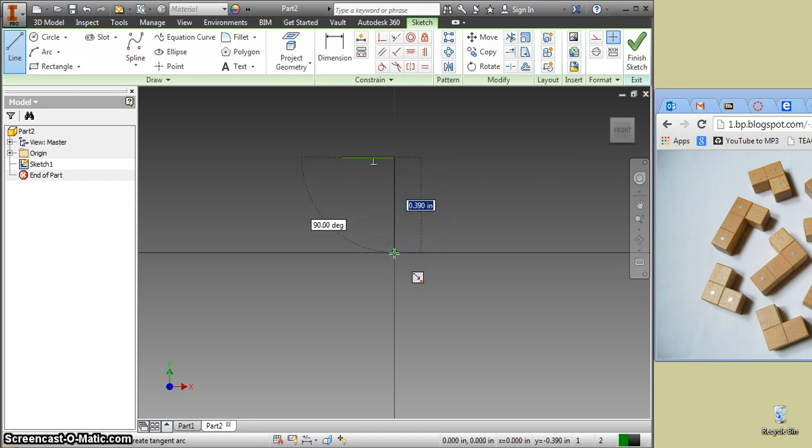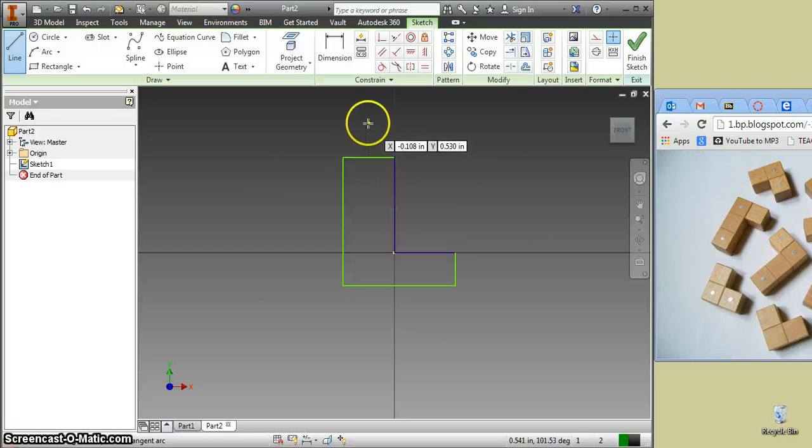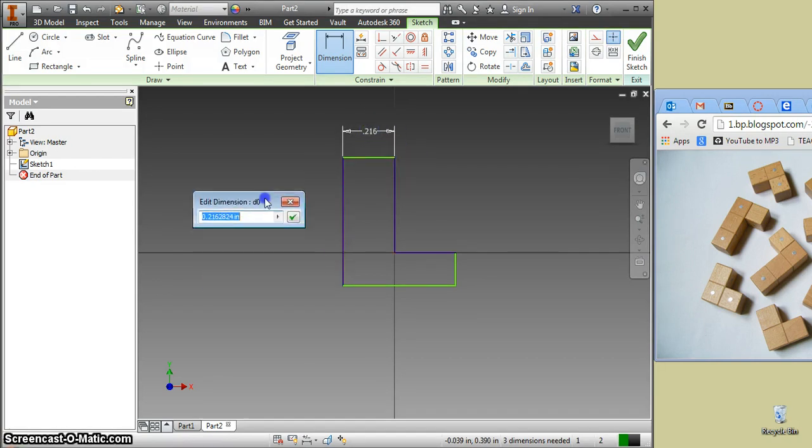So I'll go all the way down to the center point, click, drag out, make sure that I'm at a straight line, click down, and you can see that I get this dotted line straight above my arrow when I'm lined up with my point. So I'll click there and close my shape. Once my shape is closed, I won't have that line anymore. Now I can use my dimension tool to tell the computer how long I want this line to be. I click on the line and drag up. Once I click, it will tell me this is the dimension that I currently have.